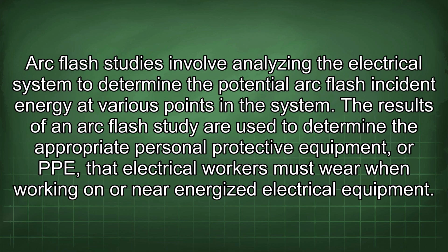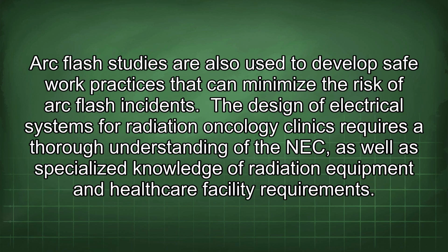Arc flash studies involve analyzing the electrical system to determine the potential arc flash incident energy at various points in the system. The results of an arc flash study are used to determine the appropriate personal protective equipment, or PPE, that electrical workers must wear when working on or near energized electrical equipment. Arc flash studies are also used to develop safe work practices that can minimize the risk of arc flash incidents.